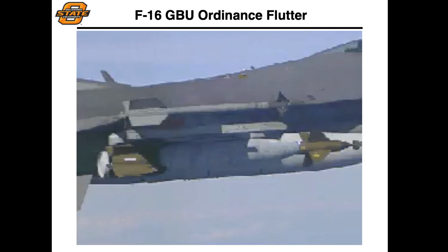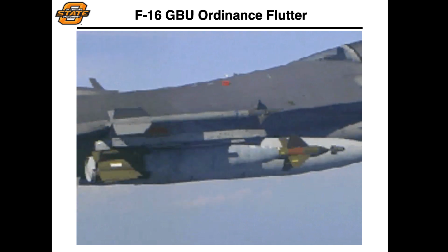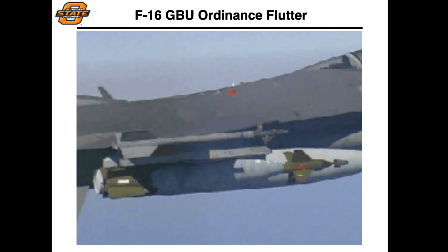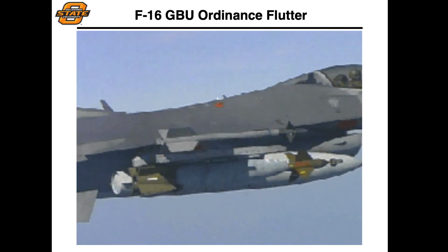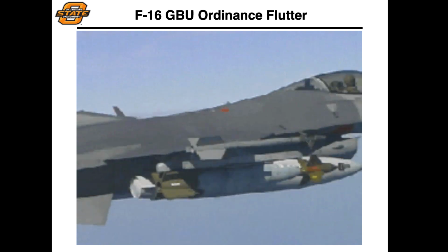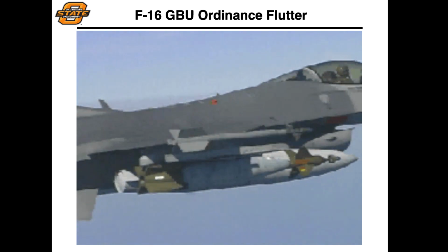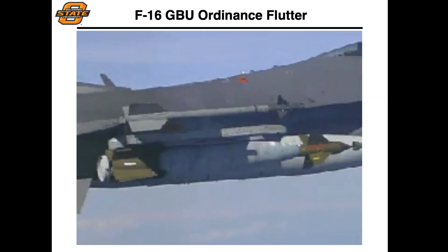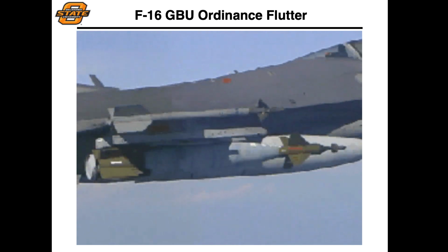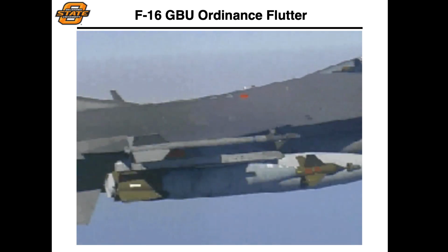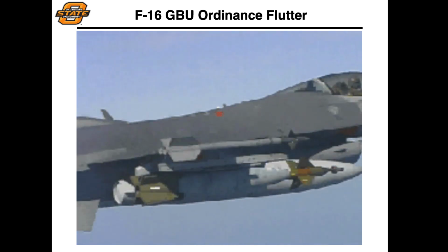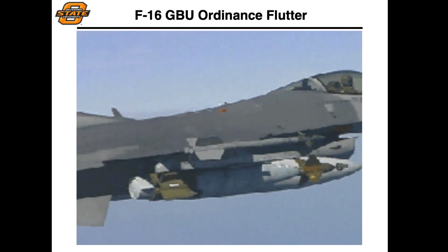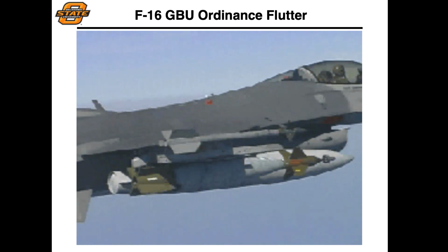And where this really becomes important then, if you start to look at the fatigue impact that this is going to have, rather than having your aircraft now have cycles on the order of ones or tens in a day, now you might have cycles that are happening on the order of hundreds, thousands, or even 10,000s during a single day. So this can reduce the overall lifetime of your aircraft. So these things must be taken into account as you go through this process, even though it's really far beyond our ability to analyze at this particular stage in our studies.